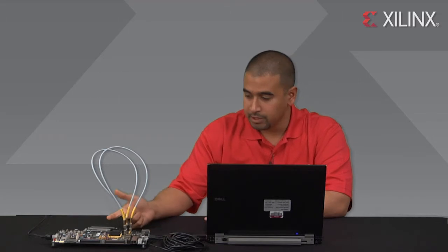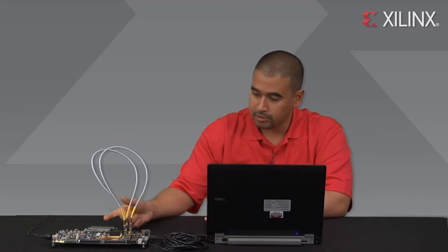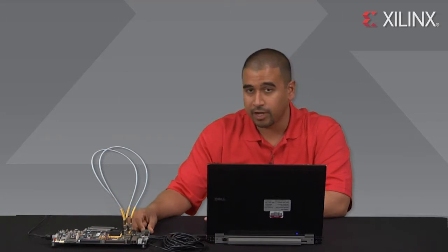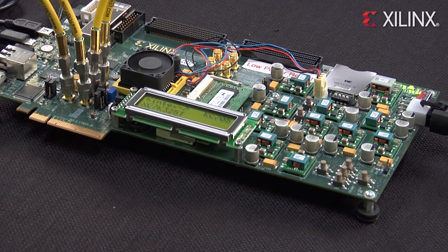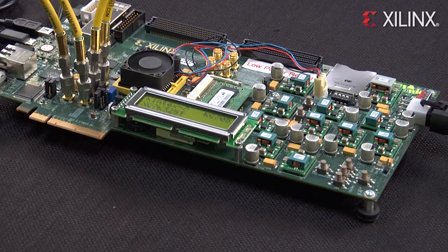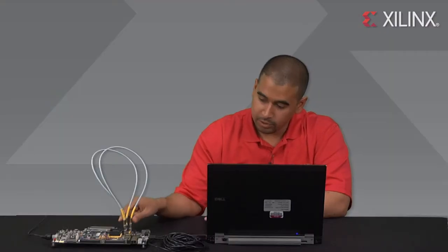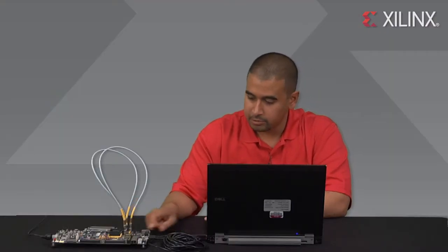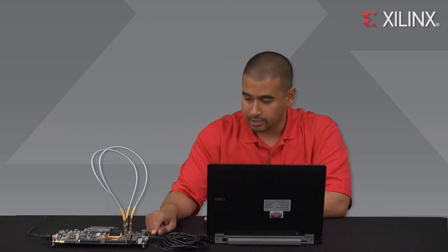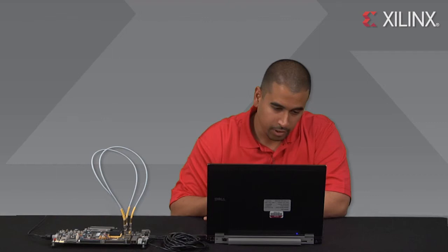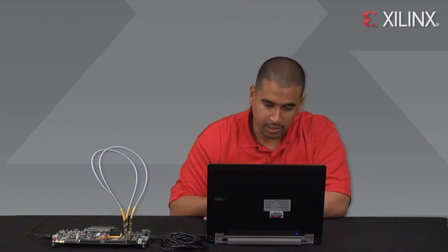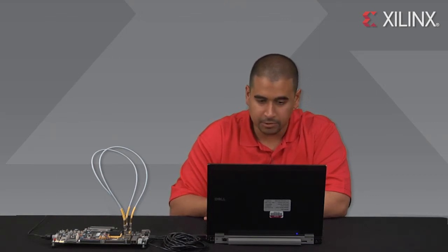We're going to go through some of the power measurements on this board, which is built into the KC705 board. We've got power measurement capabilities. It's great for doing evaluations on how much power your design is actually consuming. Through the digital power regulators, we can actually read the data out of this USB cable and onto this GUI, onto the screen. We're able to display VCC int, VCC aux, the I/O rails, and the MGT rails.